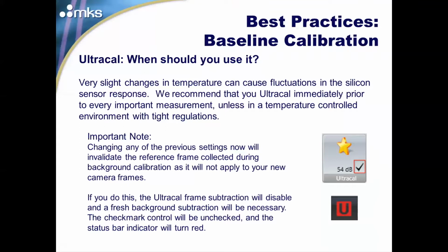If you meant to do that, go ahead and apply ultracal one more time, block your beam, and then you can resume. If you didn't mean to do it, take note of what control you modified, and don't change that after Ultracal. You want to get your camera settings figured out, then do your baseline calibration, then move on to measuring your beam.